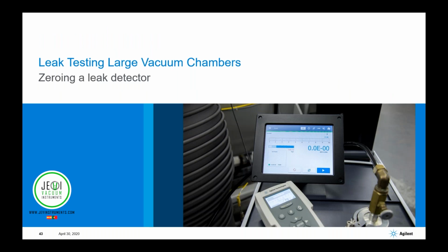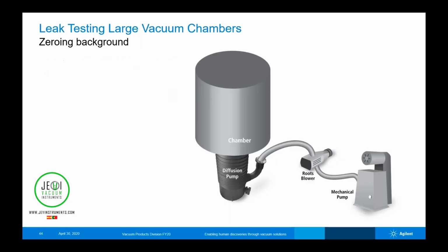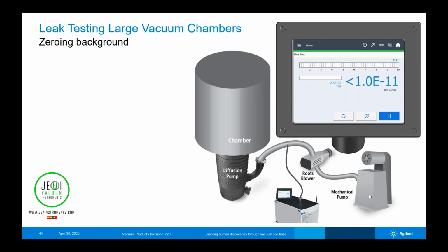Now, on a leak detector, zeroing is something we always get a lot of questions about, and I'll very quickly go through what we mean by zeroing helium background. It's something that can save you a tremendous amount of time when you're leak testing a large chamber, and that's because when we bring our leak detector in and we connect it in the right location,